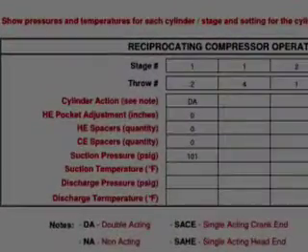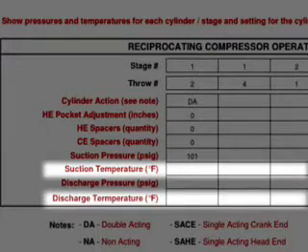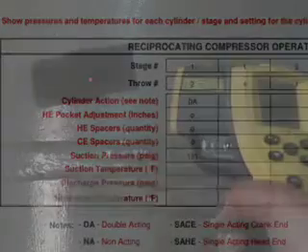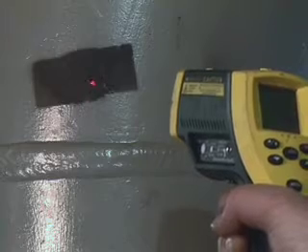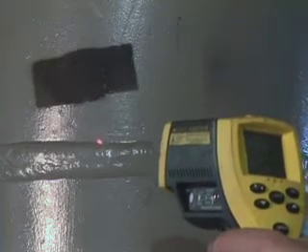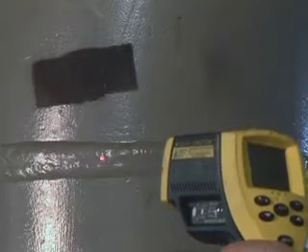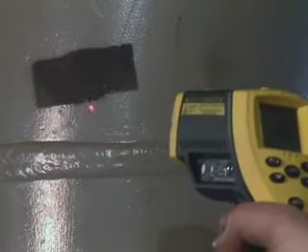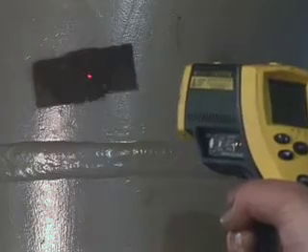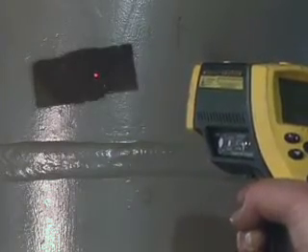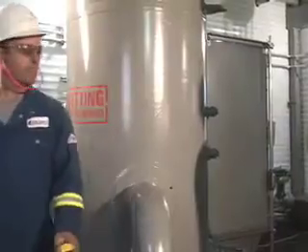Temperatures should be taken with an infrared heat gun on a dot of flat black paint provided by Detechtion's engineers at the time of audit and initial setup of your compressor on the Enalysis system. Paint color can affect the readings on your gun by as much as 50 degrees Fahrenheit. Heat guns are calibrated to record the absolute temperatures of black bodies, which is what our system requires.